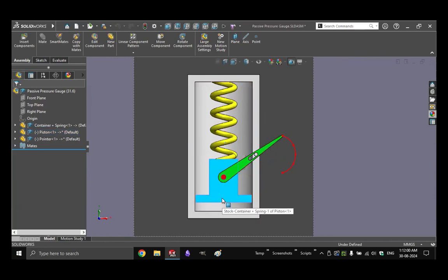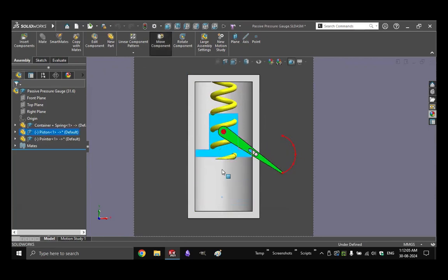It's going to compress and decompress when this moves. So forget about all of that. What's the driving force here is just the linear motion of this component up and down. So that's what I want to do. All I want to do is just move this from up to down. So obviously I can just add like a limit distance mate and use that to drive the animation.